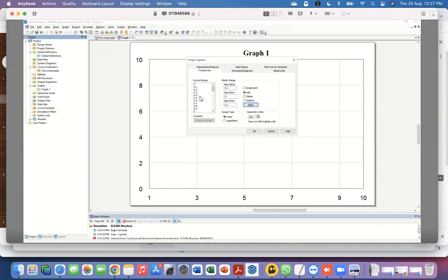the same resolution in the frequency spacing for different ranges of frequencies. So maybe there is a particular range of frequencies, say between 6.4 and 6.5, where you expect some feature to come because of your previous analysis of the circuit. And you can do over there something which is finer. So let's say I go from 6.401 to 6.499. And here I want to do it at 1 megahertz spacing.